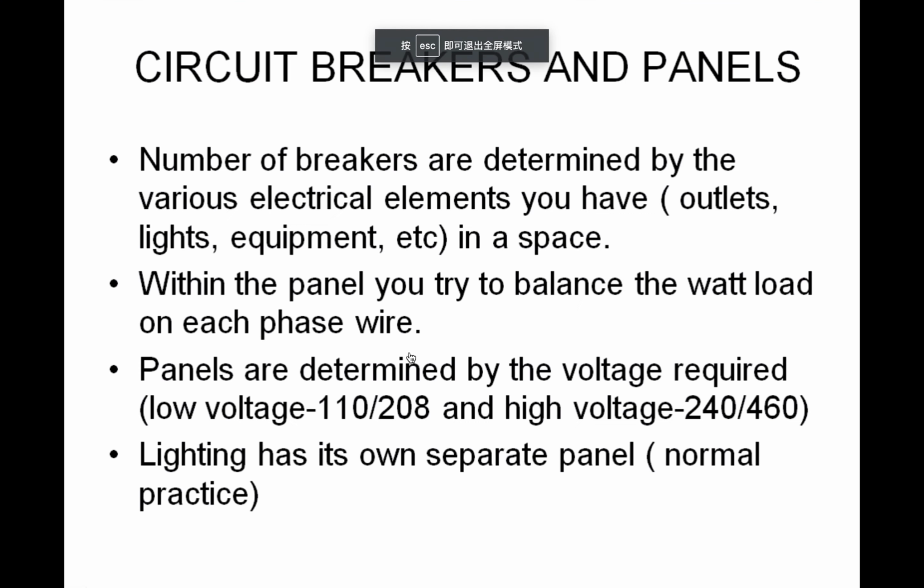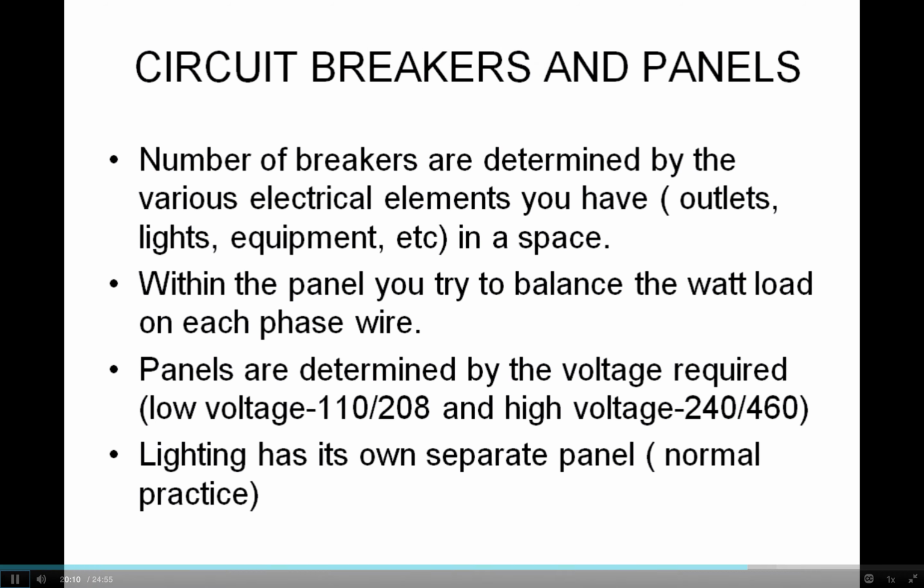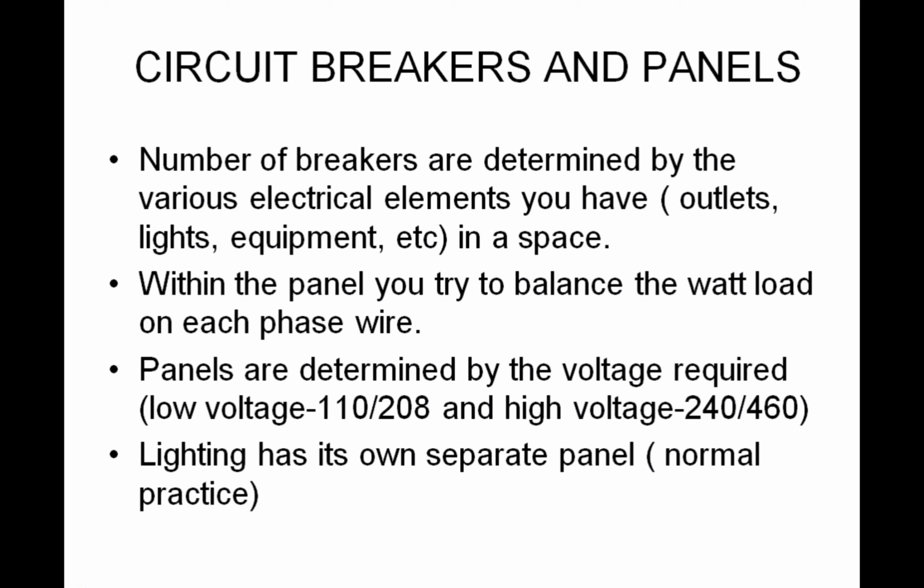And it trips a breaker, what'll happen is every third light will go out and the other two will remain. So what you want to do is you balance it out so that none of them get overloaded, and you can maintain all three lights, every three lights up the entire avenue.